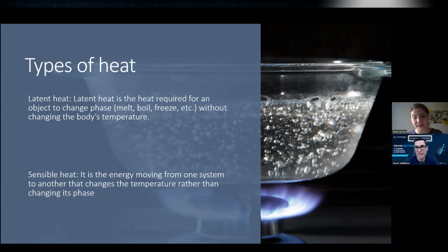won't remain constant, because in the evaporator we have latent heat and sensible heat, if it's direct expansion, because we want superheating at the outlet in order to make sure that the compressor won't have any liquid, and also for the thermostatic expansion valve to work.